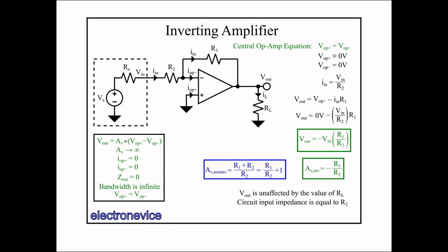It is also worth noting, at this point, that inverting amplifiers have a very small common mode input voltage range, very close to ground regardless of what Vin is, whereas non-inverting amplifiers have a common mode input voltage that varies just as widely as Vin does. This makes inverting amplifiers more advantageous in some ways than non-inverting ones, though the reasons why are a significant non-ideality and therefore will be discussed in later videos.